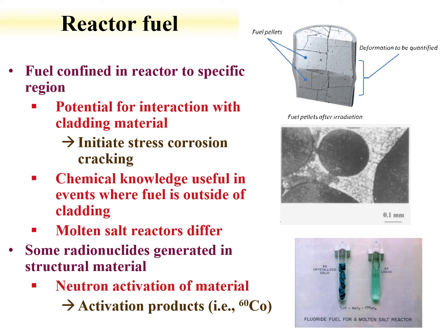Another interaction, once we have some interface between the fuel and the cladding, is that the chemistry of the fuel can start influencing the cladding. So if you start making elements that start having larger reactions with your cladding material, which is generally a zirconium-based material, you can start changing the chemistry of the cladding material and the fuel itself right at that interface. So this stress corrosion cracking is an effect, and this chemical interaction is the fuel cladding chemical interaction.